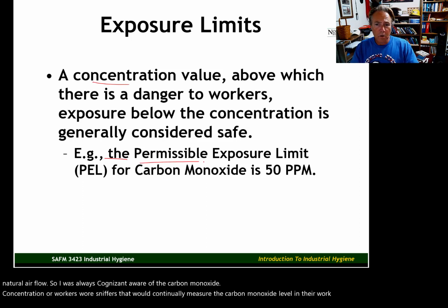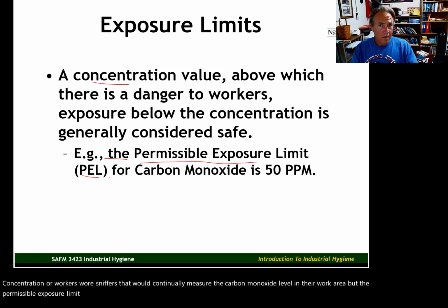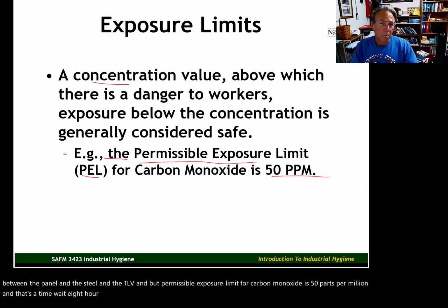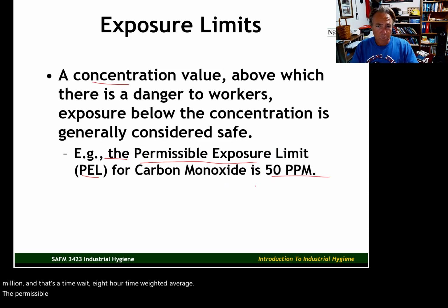But the permissible exposure limit, which is the OSHA exposure limit, and that's all I'll say now. I could do 30 minutes just on the difference between the PEL and the STEL and the TLV and so on. But permissible exposure limit for carbon monoxide is 50 parts per million, and that's an 8-hour time weighted average.